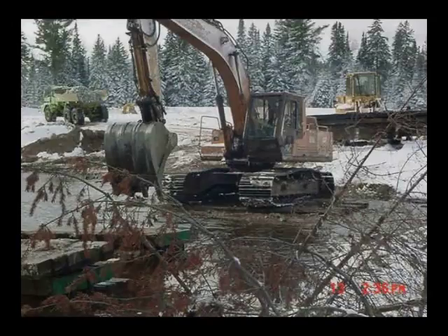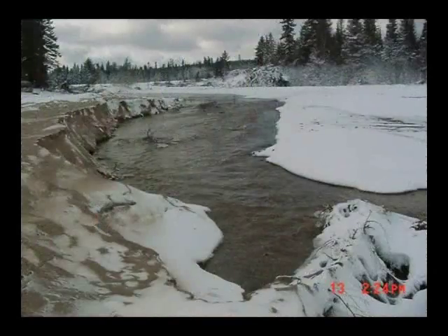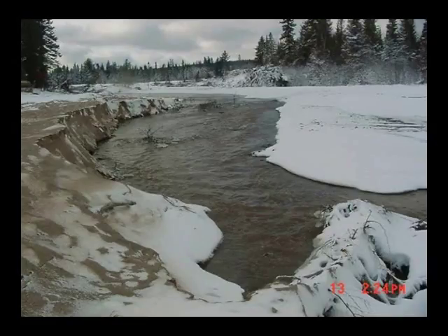Inspections must also continue through the winter months if construction is ongoing. If construction has ceased through the winter months, the site is temporarily stabilized and the ground is frozen, inspections are not required. However, the inspector is still required to fill out the inspection report form documenting that conditions are such that it is unlikely for a runoff event to occur. Anytime there is snowmelt or precipitation that results in runoff, inspections must resume immediately.